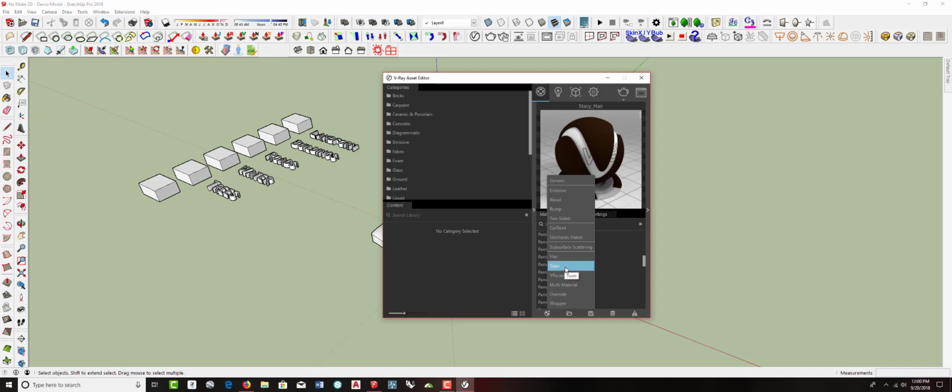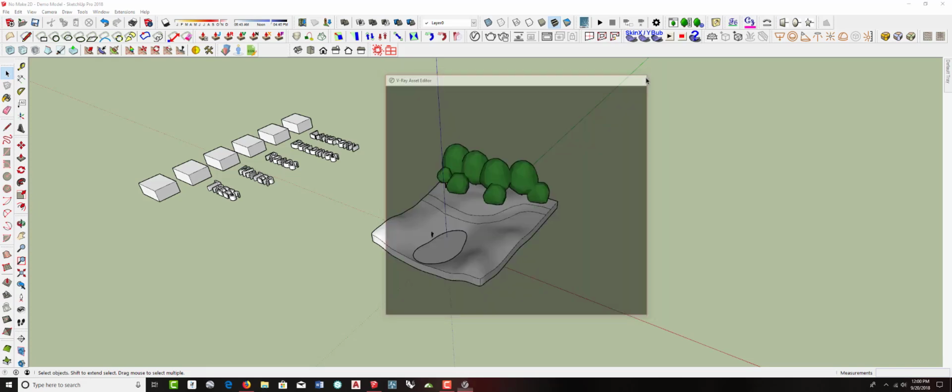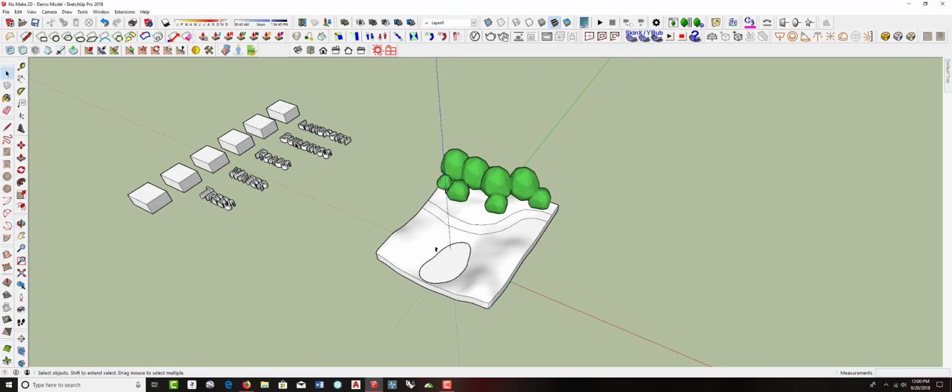And this is designed for cartoonists because, as you know, if you've looked at cartoons, they have simple color fills and they have lines around them, and they use line weights, heavier line weight on the profiles in order to distinguish them. So I could start right here in V-Ray. What I'm going to do first, though, is just go through and pick some colors for these different elements that are in my simple diagram: landform, buildings, roads, water, and trees. Now, the other thing that kind of helps you, I've created these boxes just as a way to set up the Toon materials, and then we'll apply them.